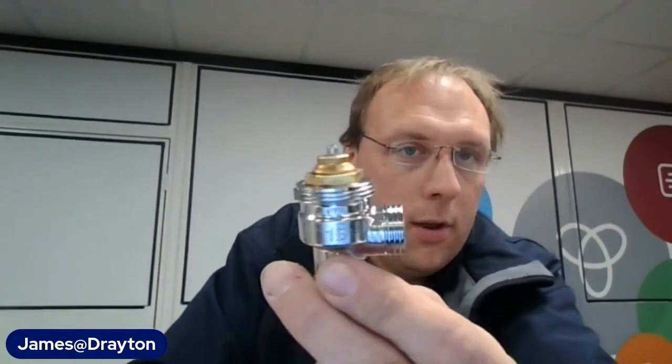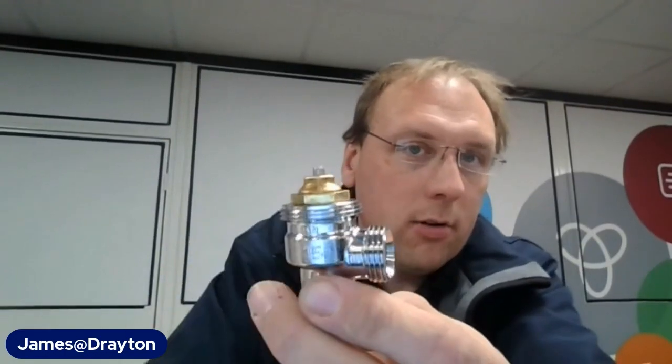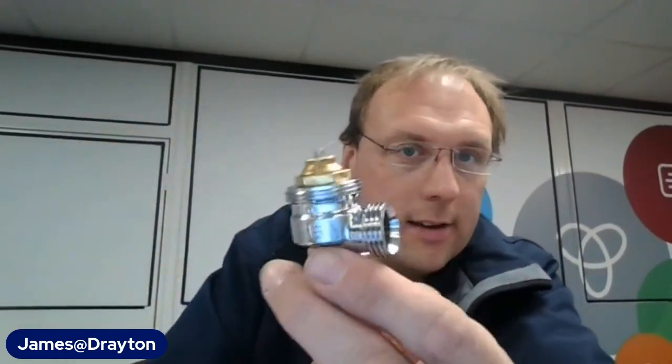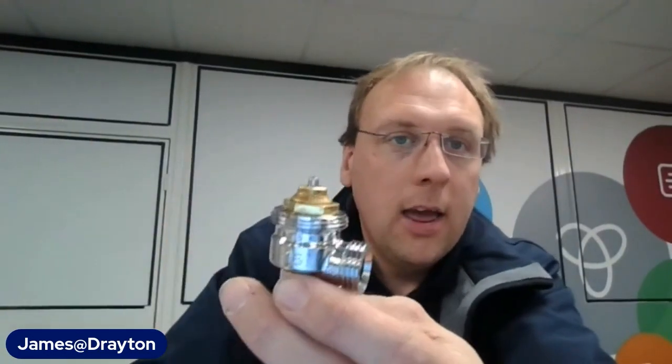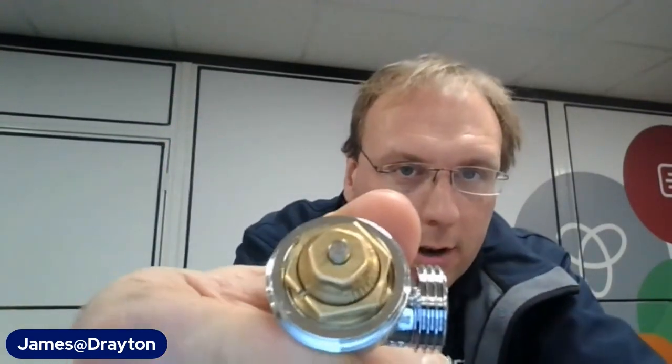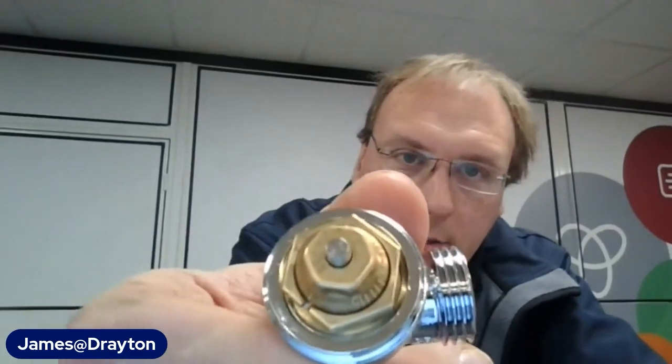Now this one, whereas the other one is sort of fixed balancing, so you pick an aperture size and that is fixed. With these, the aperture is always varying. So as temperature and pressure rises in the system, the aperture will change to make sure that you've got a fixed flow rate into the radiator. If you know what the output of the radiator is on the box that these come with, it tells you what setting you need to set the top to. And again, you can use the tool, or indeed an 11mm spanner will allow you to turn that insert. So you can go anything from 10 liters per hour to 150 liters per hour.